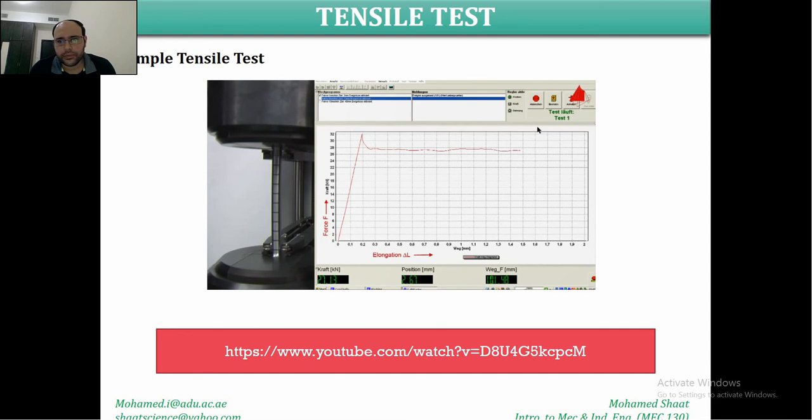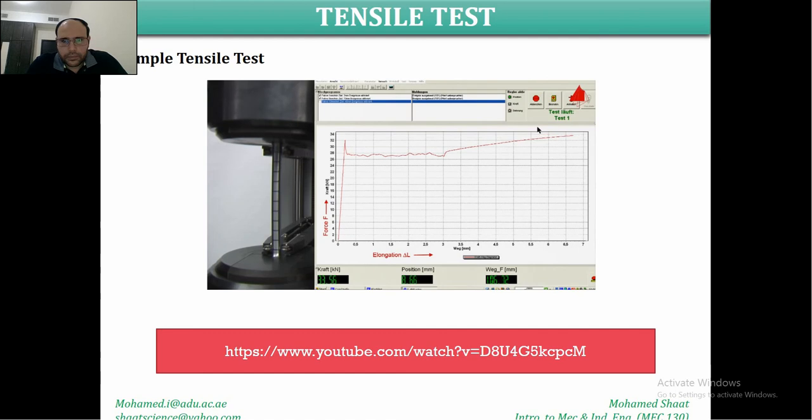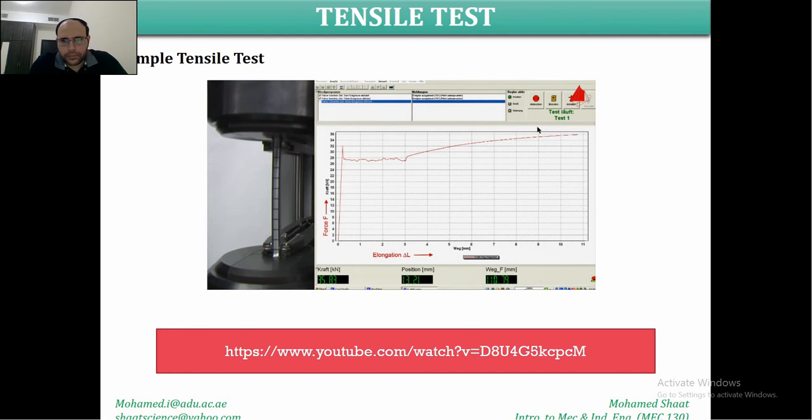In the next stage of the tensile test, an almost constant force level with slight fluctuations occurs. This phenomenon is called the Luders effect. After a certain strain, known as the Luder strain, the force increases again. The material opposes an increasing force against the imposed elongation. It strain hardens. Up to the point of maximum force, the test piece is strained uniformly along its length. This means that the test piece gets longer and thinner but keeps a cylindrical shape.